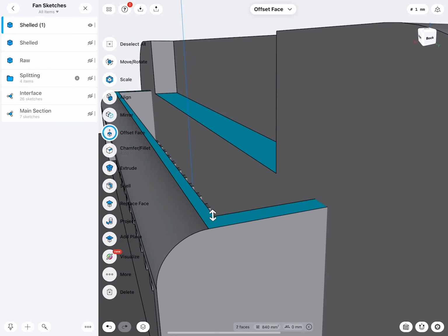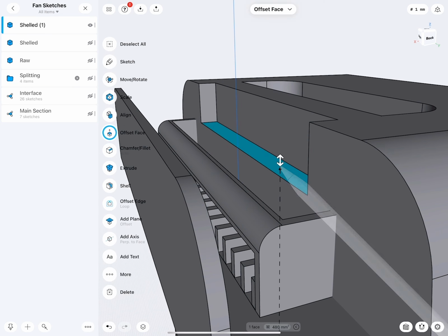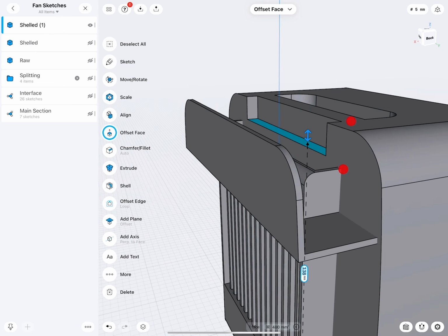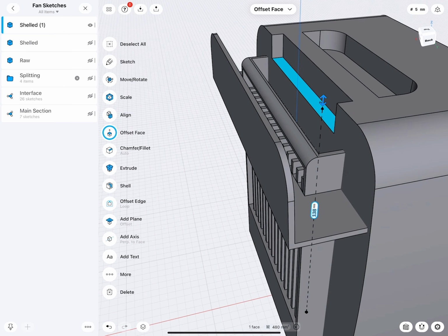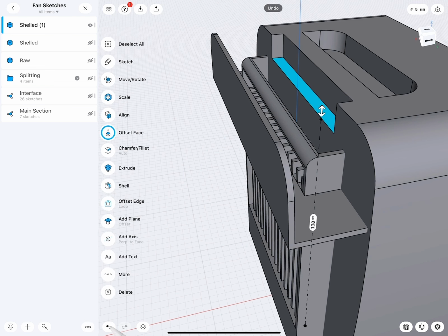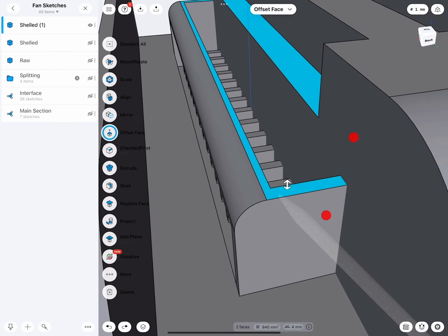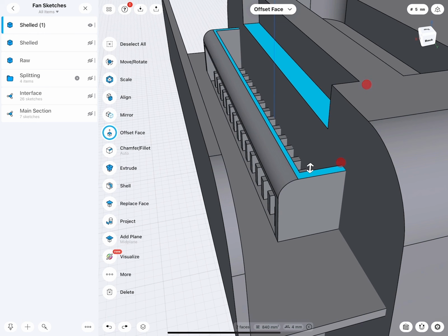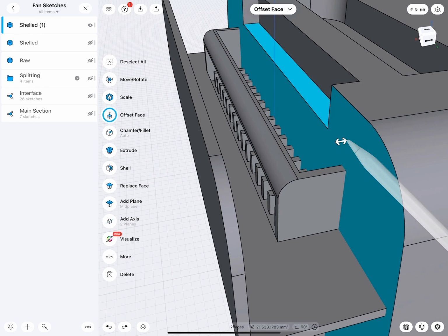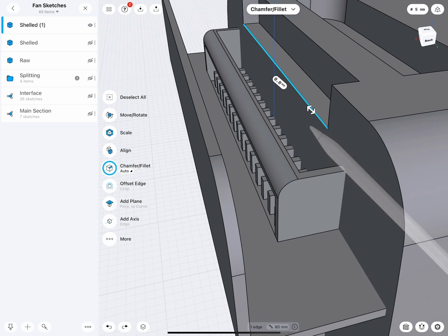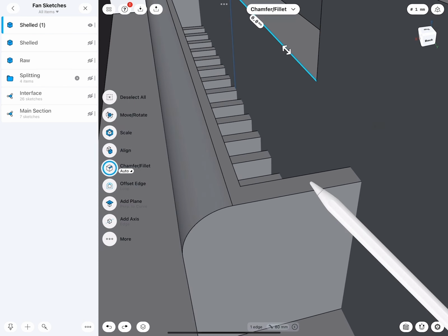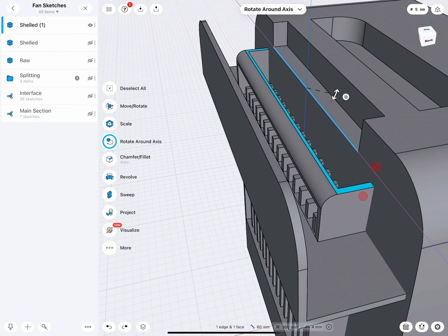So this is basically at the same plane. I need to add 2 millimeters of material thickness. That's basically kind of like the distance. And then also we would like to have a tolerance. So if I undo this actually one more time, because when I figured out that this is just 4 millimeters of a distance, and then from here later when we shell, this line goes down 2 millimeters, that will be just a 2 millimeter distance to here. So we have good tolerance.